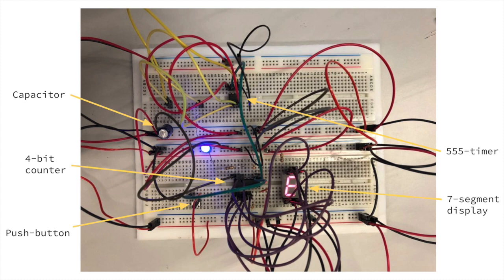Our circuit counts from 0 to 9 at a moderate pace. However, if we connect our button and push it, the counter stops. Then we exchange the 100 microfarad capacitor for each of the others listed. We notice that the more capacitance, the slower the counter. This makes sense because the more capacitance, the more time it takes to charge and discharge the capacitor.